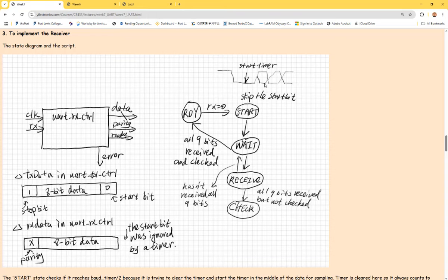Right? Does that make sense? You do the middle first, and every time it's going to hit the middle. If you do the half for the first and full width for the following ones, you can always hit the middle. So it's always waiting until the middle of the bit width and latching it.